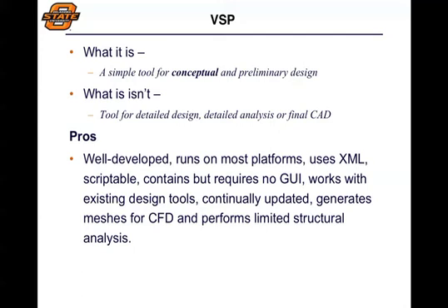Now, it is scriptable, and what that means is you can take output from another program, such as MATLAB, and have that feed into VSP, so you don't have to run the GUI on VSP. You can have the script go into that and generate that output automatically. So if you're doing a lot of optimization, you'll want to generate a lot of different conceptual platforms and designs. You can put that in as a larger program. And again, we won't be doing that for most of what we use VSP for, but it does become very, very powerful. And so it does interface with those existing design tools as a part of that.